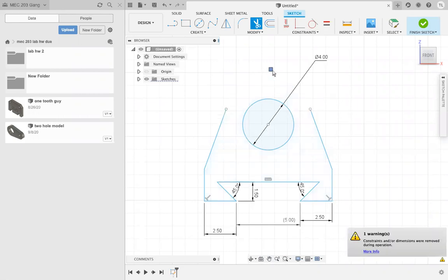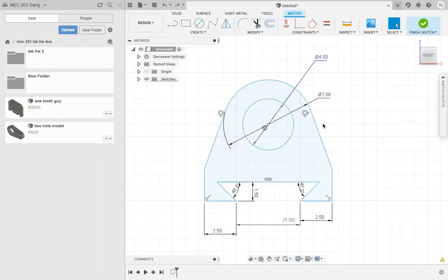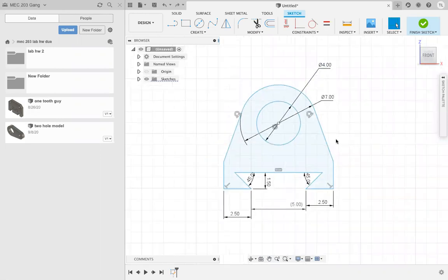So one thing you're missing is that, as you can see in this part of the drawing, let me make it bigger. It's not one uniform contour like that first bracket was. This is actually 3 separate contours. You have the contour here, and the center circle, because when you extrude this, which we'll see later, that is actually 3 separate bits. You can see this on the version I made, how you have a line that goes through here and a complete circle, because although not visible in 3D, these are all of a slightly different topography, the center one being slightly taller than the